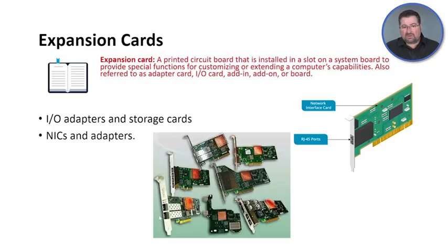So we see a whole plethora of expansion cards down here. Some are for sound, some are for USB, some are for graphics, obviously. That's going to be your most common type of expansion card, your graphics card, which is going to use that x16 PCIe slot. This one is a network adapter card right here. It's to plug in a cable, RJ45 connector on the end, into the network adapter so you can plug into a wired network.